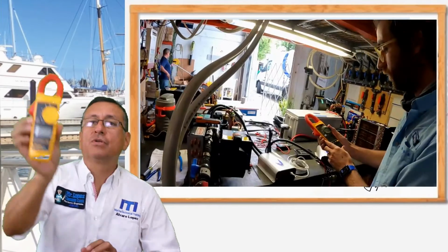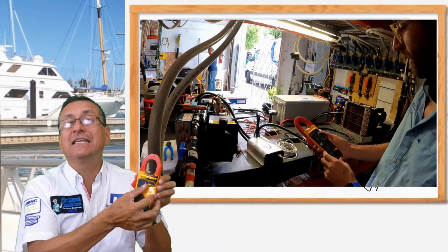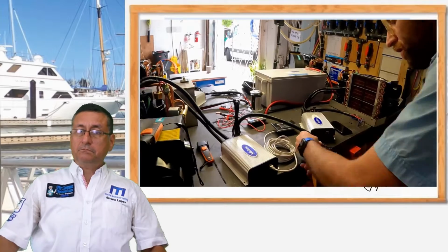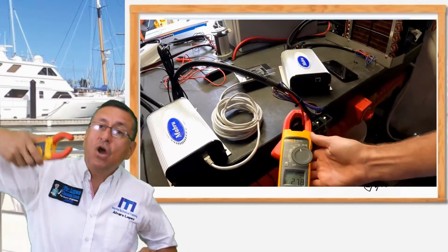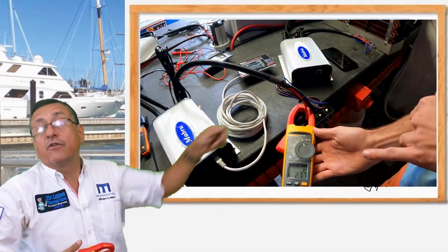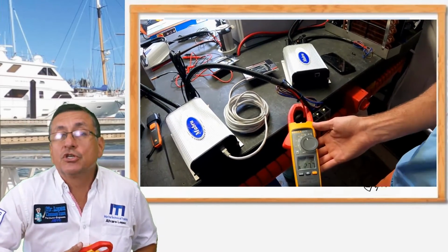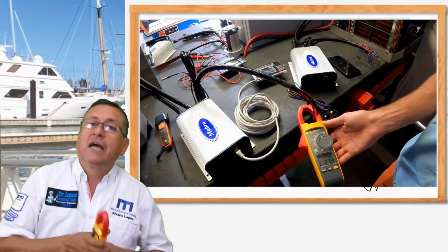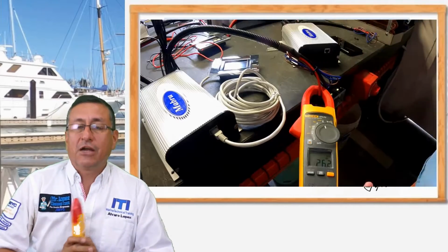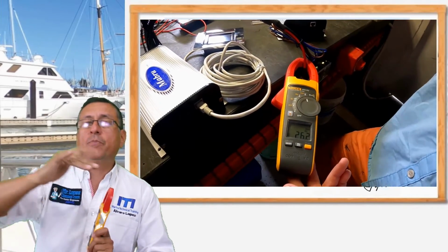We are going to use the clamp, and we are going to select amps AC, that one. Alright, and we are going to hook the clamp in the cable coming from the breaker. That's the cable entering in the thermal switch. In that cable, and you start the air condition, and you can read the consumption in amps at the peak, and after that at the operational temperature.